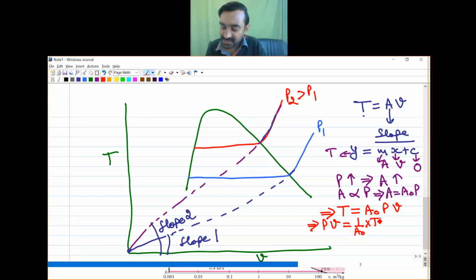Okay. Now, if I see the ideal gas equation, we already know that PV is equal to RT. So in case of our steam also, we have a certain region on the superheated temperature table, a superheated zone, where the behavior of water in vapor phase is identical to that of an ideal gas.